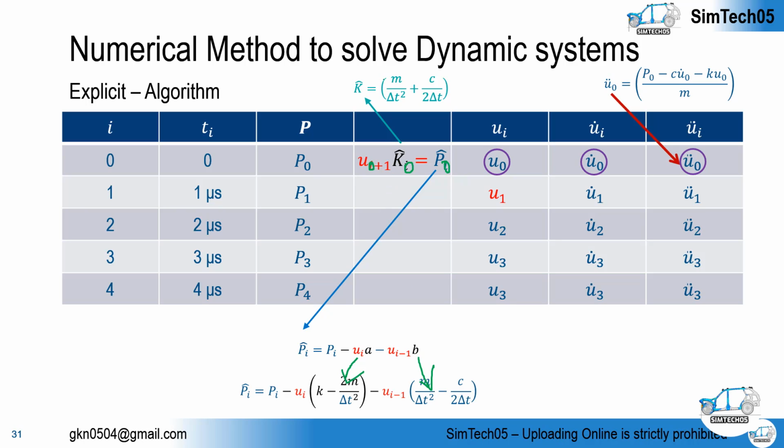So the K we can find from the given values of mass and stiffness matrix as well as the time increment, actually not time period. Now talk about this P cap. In this P cap, let's put i equal to 0. So P0, do we know the P0? Yes, of course we know the P0, the load applied in the previous increment.